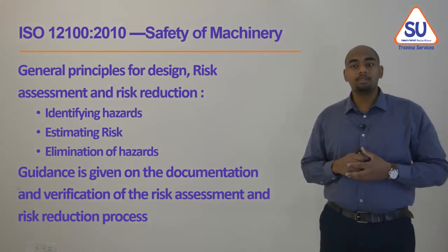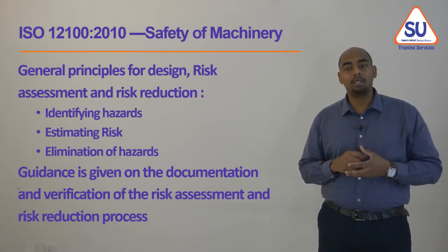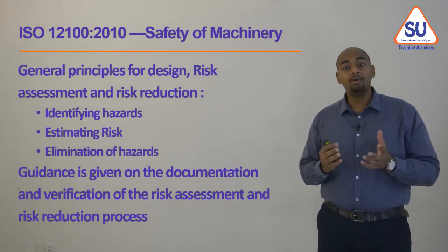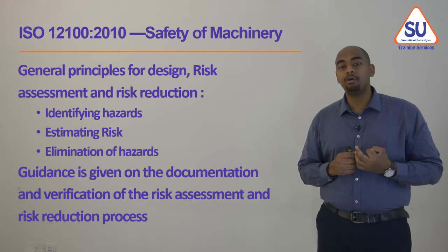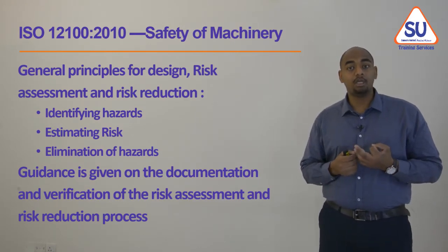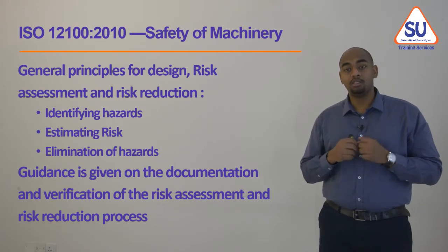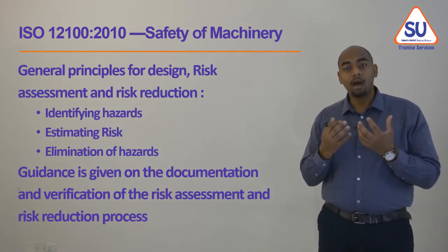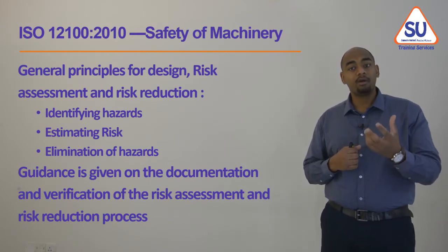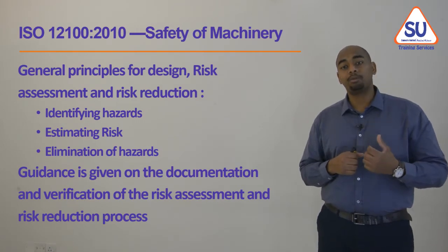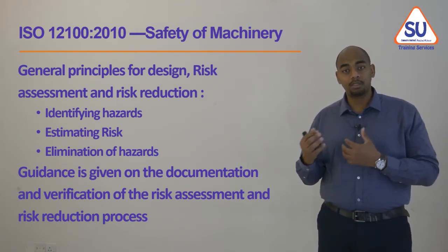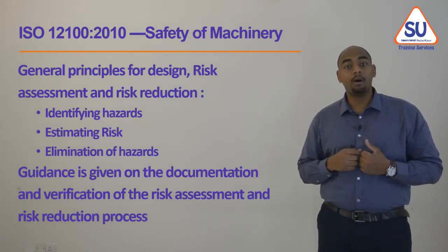Also, on the general principles for design and the risk assessment technique, the risk reduction should be clearly covered while we design those machineries safely, by the identification of the hazards, the estimating of the risks, and elimination of those hazards from the machinery by a very good design stage. So this ISO standard provides guidance on the documentation and verification of the risk assessment and reduction process while we design those equipments for our customers or for the market in general.